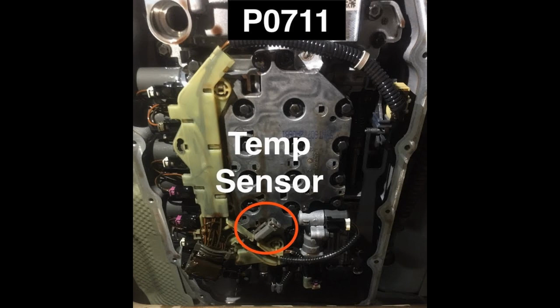Condition 3: a transmission fluid temperature at startup is 129 to 149 degrees Celsius (264 to 300 degrees Fahrenheit). Vehicle speed exceeds 8 km per hour (5 miles per hour) for a cumulative 300 seconds (5 minutes).